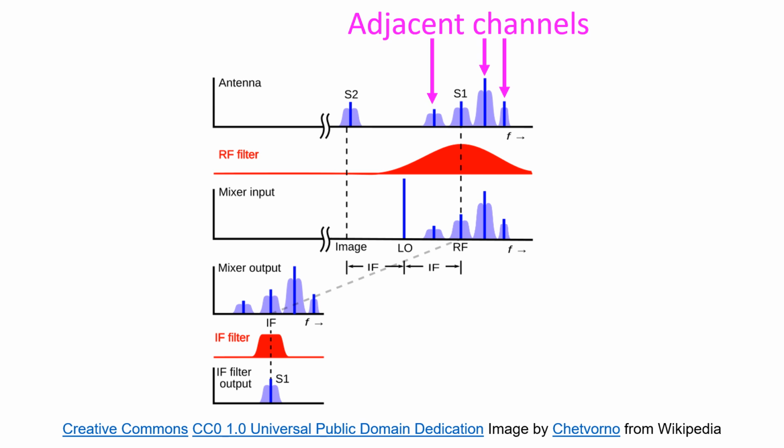We observe this problem in amateur radio mostly on contest days when there are plenty of stations using the limited frequency band available. If another SSB station is operating at less than 5 kHz difference, adjacent channel interference is quite common. Very strong stations can interfere with reception of weak stations on a nearby frequency.